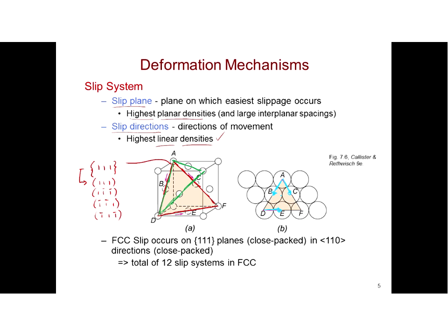Agreed? The plane, and we've talked about this before, extends forever outside of the unit cell in all directions, right? And so as you look further, we've talked about what the stacking looks like, and this would be one stack in the FCC stack. It would be one of the layers, and all of these are the most likely to move together because they're packed in the tightest, and so it's easiest for these bonds to stay together and these atoms to move as a unit.